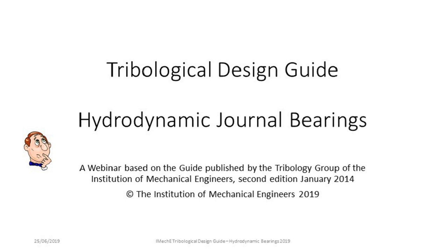if we're talking about steadily loaded hydrodynamic bearings, I mean, normally when you design a tribological pair, you're thinking of making one of the surfaces possibly sacrificial. So if there is wear, you can replace one of the components relatively easily. Yeah. And usually the shaft is the more expensive component.